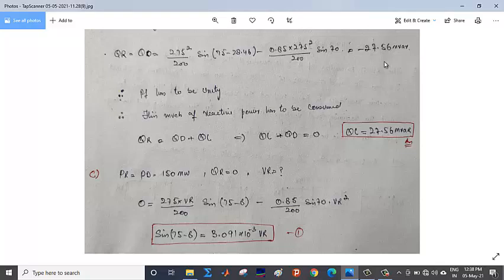That means without a compensating network or compensating equipment, the reactive power is negative. That means the load is supplying reactive power back to the source. So this much reactive power has to be consumed. I have told you in the beginning that when the reactive power is negative, it has to be consumed by inductive reactive power, by placing an inductance at the receiving end.